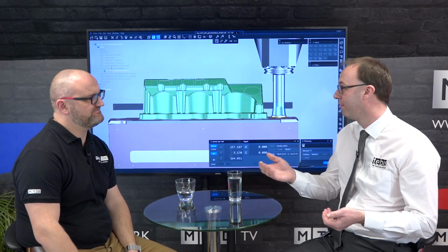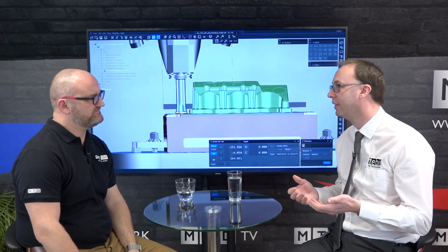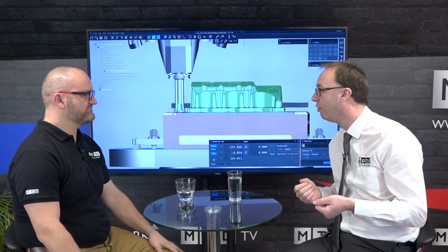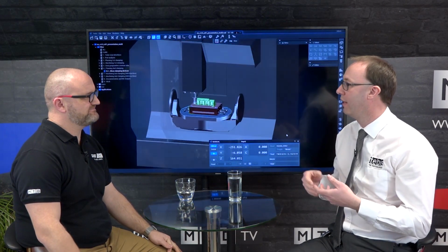Then we have things like we check macros on the machine. Now the macros could be something that's controller defined, like a tool change. Or maybe we have something historical, where the machinist has created a program or a macro himself that he likes to use.